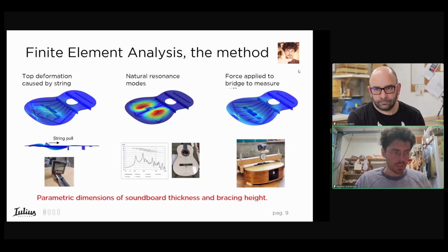And also Trevor in his book takes this into account, and he says a very wise thing: if you really are looking for a very stiff soundboard across the width, instead of choosing a very stiff wood, you can put a brace there, which accounts for that stiffness much more than choosing a wood with a large stiffness. I don't know if this makes sense to you, but thank you.